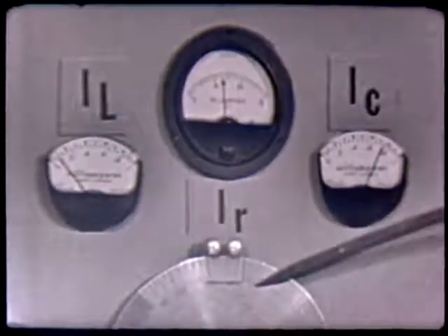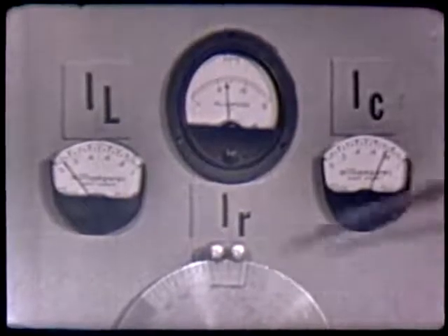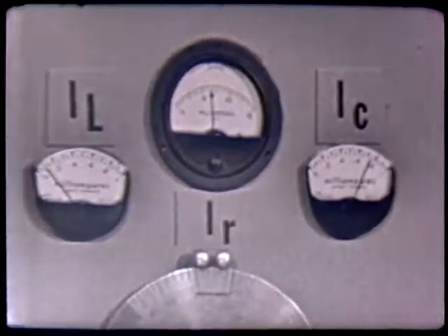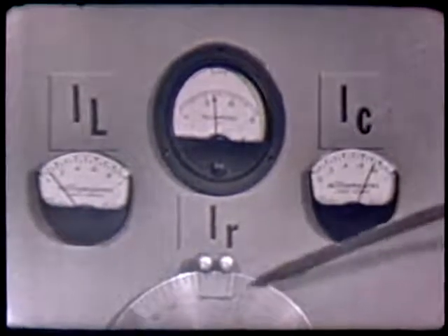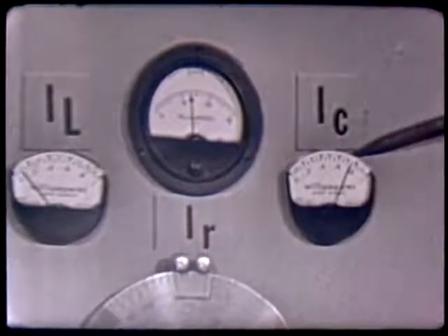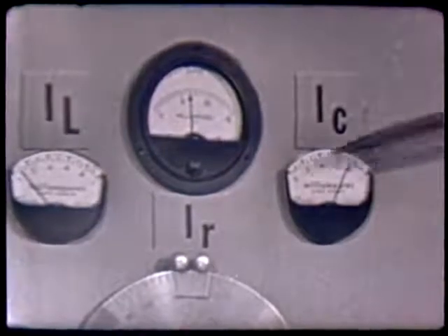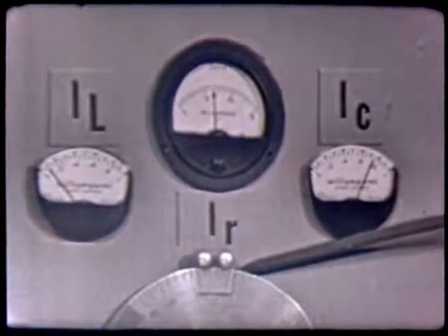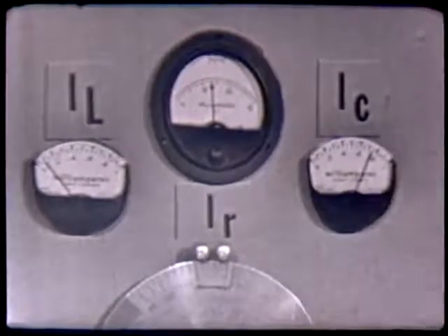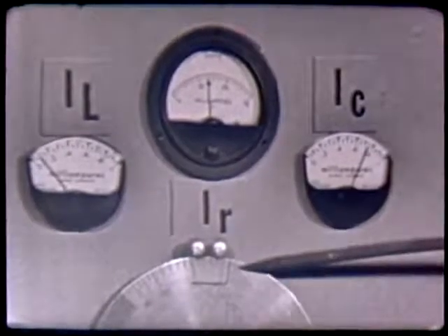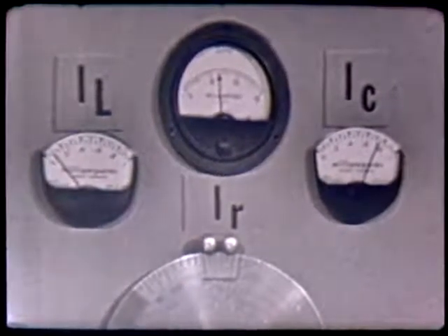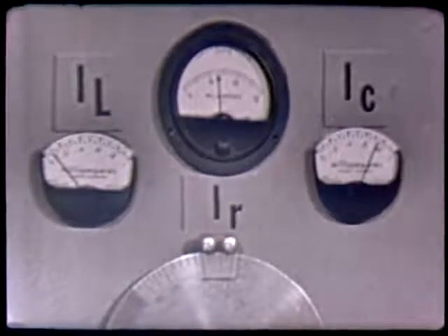Well, suppose we decrease the frequency applied to our network. What do you suppose is going to happen to IC, IR, and IL? Let's analyze the situation first and determine what's going to happen. We know if we decrease the frequency applied to our network, the capacitive reactance of the capacitor is going to increase. Therefore, IC will have to decrease. Likewise, when we decrease the frequency, we're going to decrease the inductive reactance of the coil, and IL would have to increase. But what about IR? Does frequency have anything to do with R? No, it doesn't. The only thing that's going to change the current through R is the voltage applied to the circuit. And since we are not changing the voltage, IR should and will remain the same.